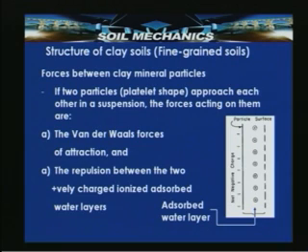The forces between clay mineral particles: if two platelet shaped particles approach each other in suspension, the forces acting on them are van der Waals forces of attraction. There will be a certain force of attraction between the particles. And the repulsion between the two positively charged ionized adsorbed water layers.